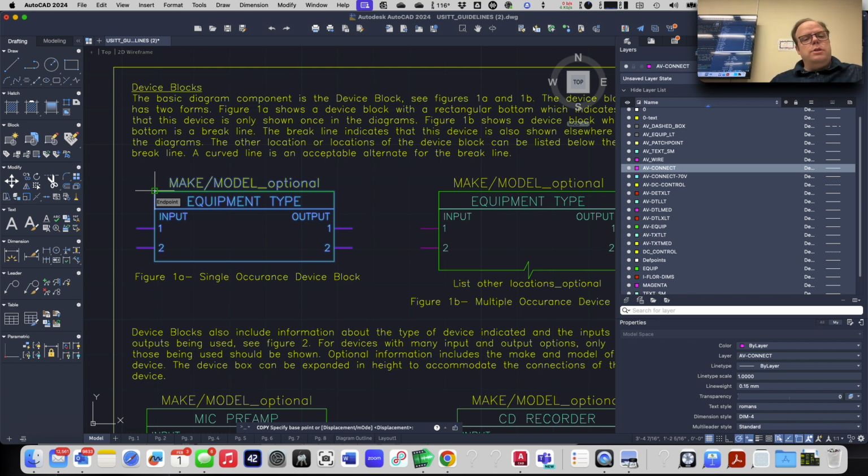One is your cursor will usually go bang. You'll hear it, you'll see it kind of jump right there. But the other thing that happens is you'll see that little green box that is the symbol for endpoint snapping. So I've snapped to the endpoint of that line. And so while I've snapped there, I can just click. And okay, that's the origin. That's where I'm going to start from.